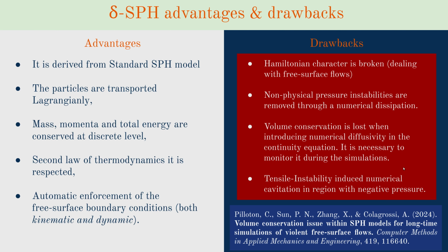Moreover, by modifying the continuity equation, adding the numerical diffusivity, we introduce errors in the link between particle position and the geometric volume they represent. Finally, all the SPH schemes discussed so far suffer from tensile instability, which, as I will show later, can significantly limit the applicability of the method in many engineering problems. I will show that in order to remove this instability, two other compromises are needed.